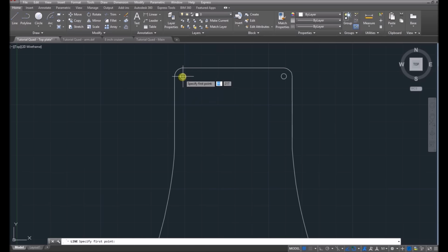Let's just do the SMA at the back. That's pretty standard. 60. So let's go 30, and then we'll come up a little bit. I think maybe like, I don't know, 5 mil. I think I said 3.5 for the SMAs. So that's where you can have your SMA at the back on this particular quad if you wanted, for your VTX.